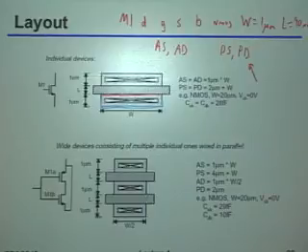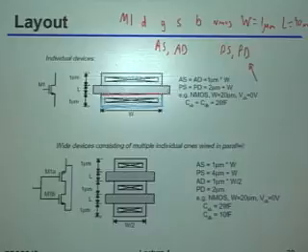By the way, anybody know why that is? Why is it that SPICE is sort of set up that way? Why is it that you might not explicitly put that inner gate edge into your instantiation of the model? Yeah, so what you said is it's already captured in the model. And the reason it's already captured is because that particular side of it has to be there. There's no way you could draw a transistor that would not have that inner edge in it. Everything else, there may be some other rules you can play around with, but that inner edge basically has to exist. So at least in 90x% of the models that I've seen, that's always captured inside of the model in any case.